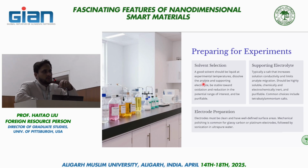Once the electrodes are clean, then only you may go for coating of your material on the electrode. The material which you have prepared, you have to coat it on the electrode, and before doing the coating, you have to clean the electrode. Otherwise, your coating will not be uniform and your coating will not be stable.